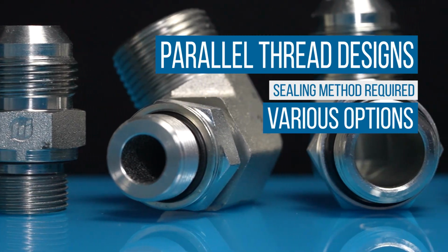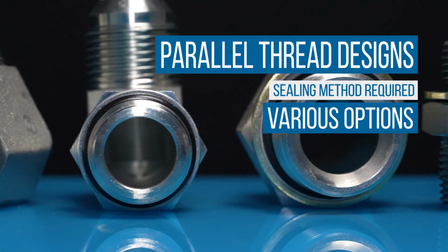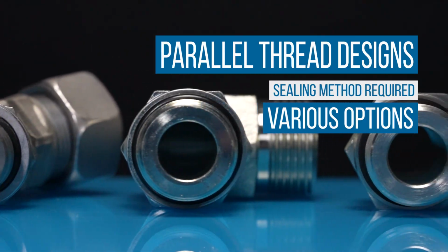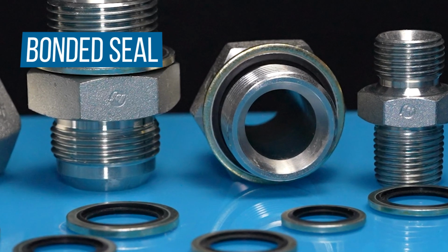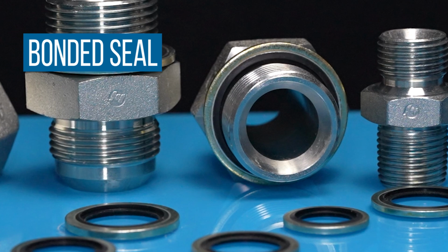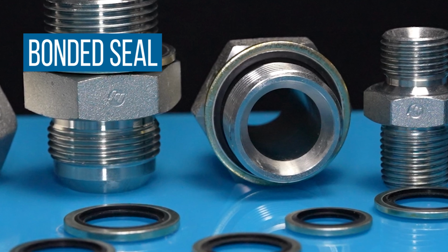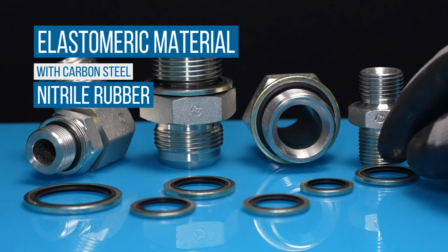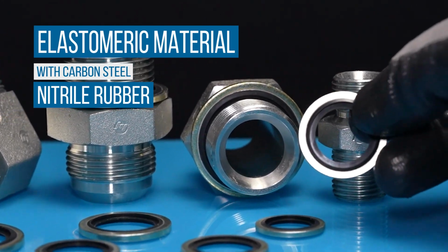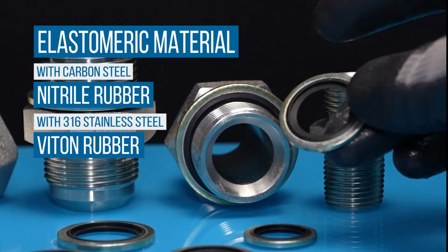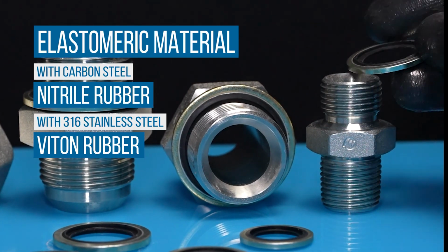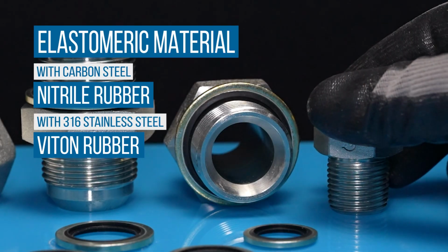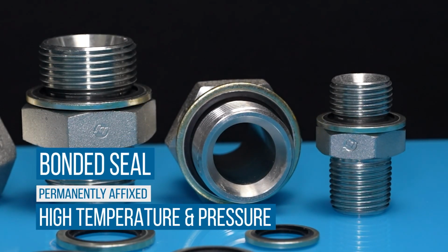British Standard Pipe Parallel, or BSPP, and metric parallel threads both utilize a variety of different methods for sealing connections. One example, a bonded seal, is an elastomeric material that is bonded to a metal washer and is used to create a seal on a threaded connection. The elastomeric material is usually nitrile rubber on carbon steel bonded seals, and Viton on 316 stainless steel bonded seals. The washer is typically made from steel, or stainless steel for more corrosive applications. The seals are permanently affixed through high temperature and pressure.